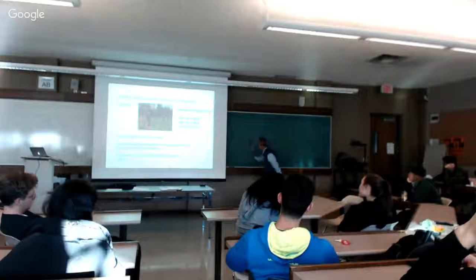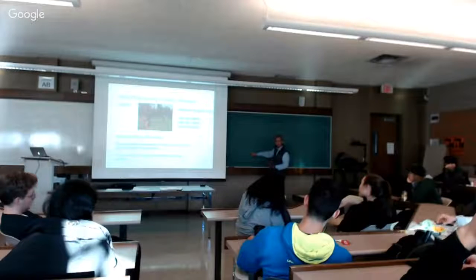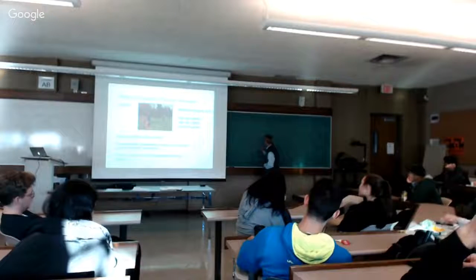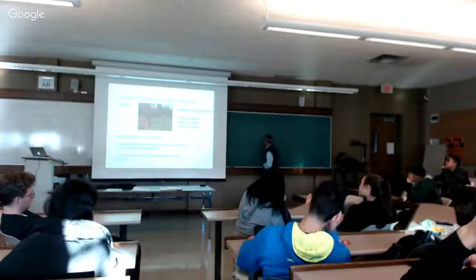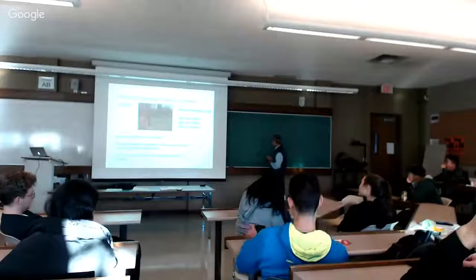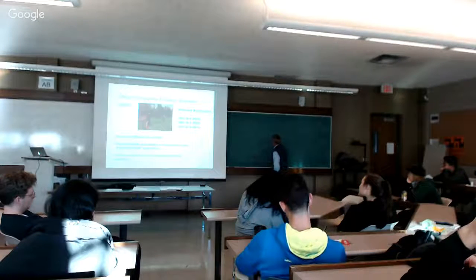And if we did the sensitivity function for this, remember it kind of goes up and down like this, where this was sort of a normalized depth, and there was a particular depth at which we were most sensitive, but we're not sensitive to stuff that was right at the surface. This thing goes to 0. So it's a maximum. I forgot what this was, but it's sort of like z equal to 0.4 or something like that, where that normalized depth is a true depth scaled by the distance between the transmitter and receiver. So that's what that sensitivity function looked like.